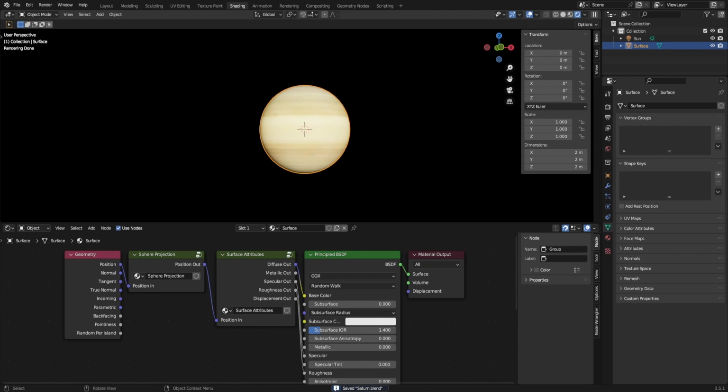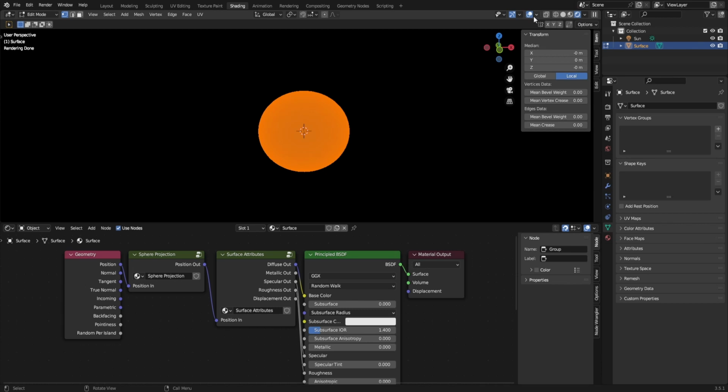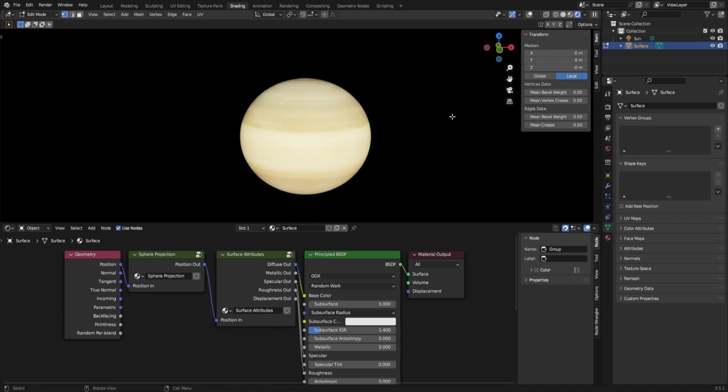And now, what you want to do, let me just copy this value. Sorry, I'm referencing another blend file of mine. That's why it might take me a second. Set the dimensions on the z-axis to 1.80407 meters. And then Control A and apply all transforms. There we go. Looks pretty good. It's nice. I'm going to hide these. Okay.